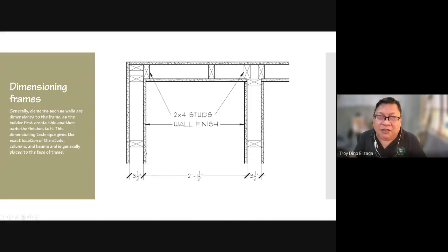But if it is this detailed, the dimensions actually start from the studs, these ones here inside. It does not include the finishing, the covering wall, because this wall can vary in thickness, and you can also put many layers here. What is necessary is these structural elements.